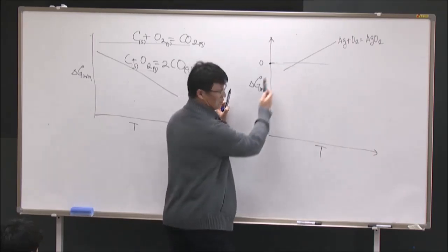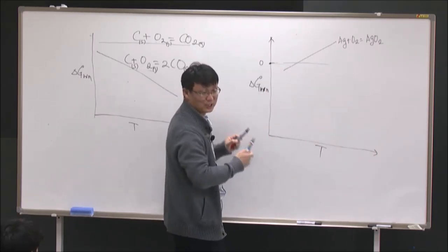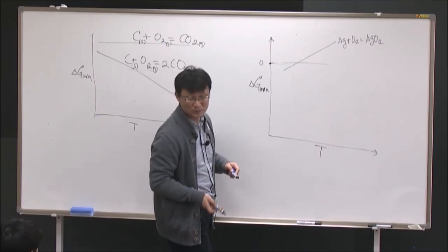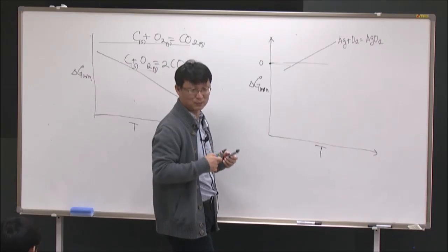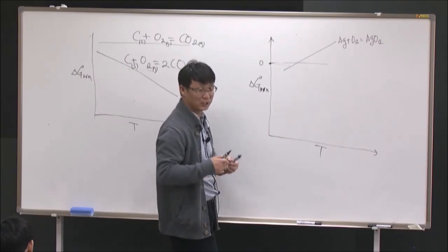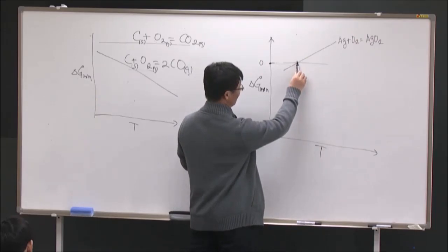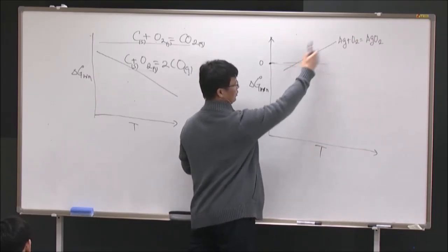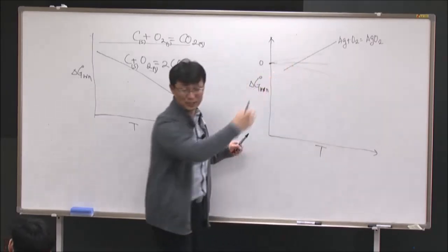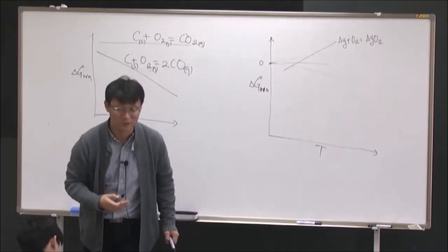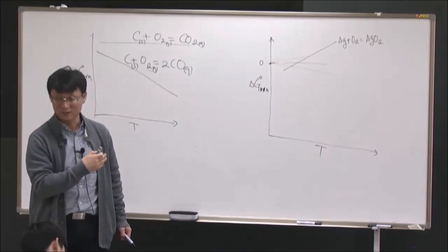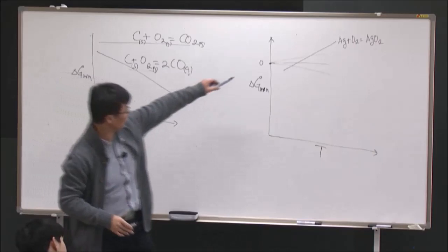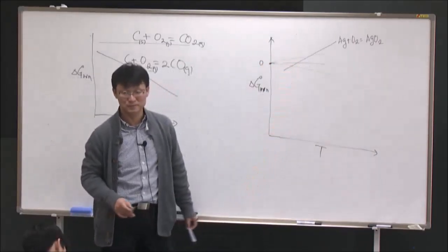Okay? But because the temperature is too low, the kinetics of oxidation are very, very slow, so there's no oxide formation. But if I want to make this chemical reaction happen more quickly, I want to increase the temperature. But when you increase temperature, your PO2, 0.21, is here, and all this reaction occurs above even 1 atm of oxygen. So typically, silver cannot be oxidized under normal conditions. Silver is one of the top ones in the Ellingham diagram.